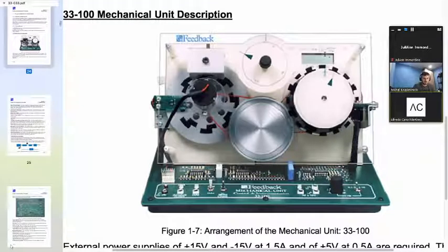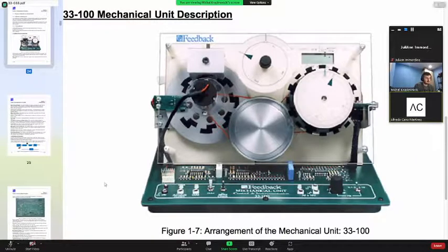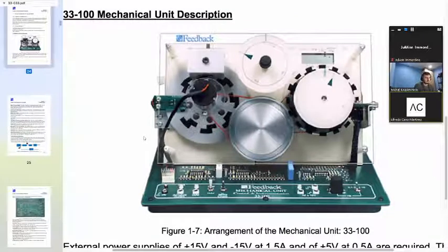So this motor will align itself according to the magnitude of the input. You see how this plays out. If the input is 1 volt and you want this motor to output 1 volt, then if the control system is designed properly, this voltage potentiometer should give you as close as possible to 1 volt, right? So this potentiometer will behave depending on the magnitude of the input voltage.